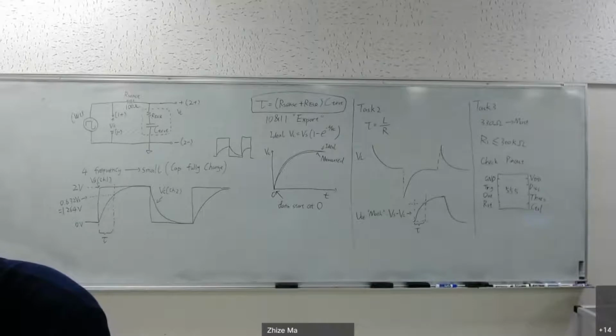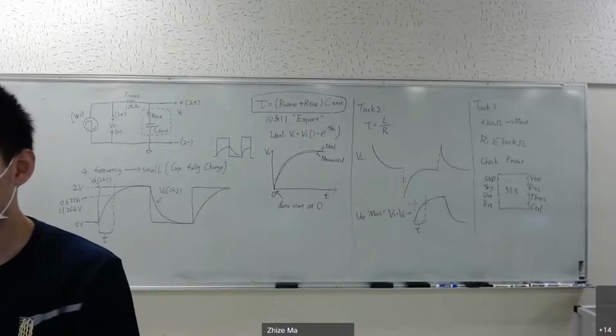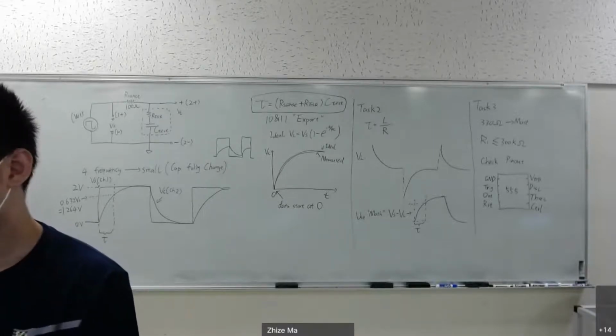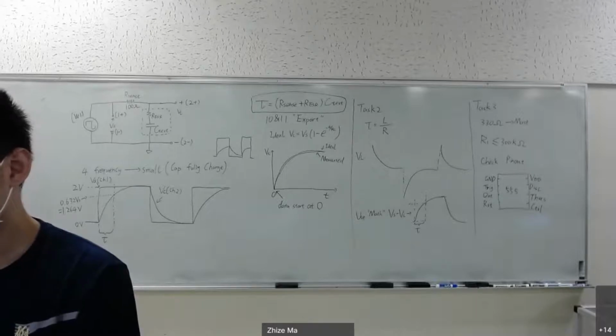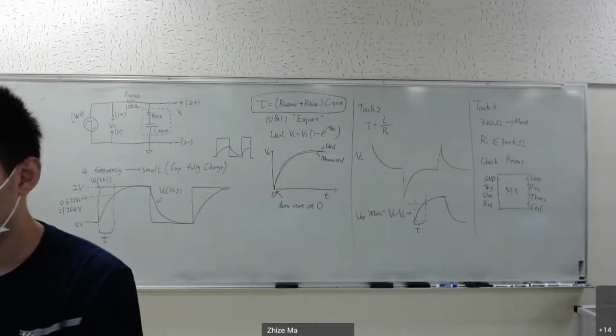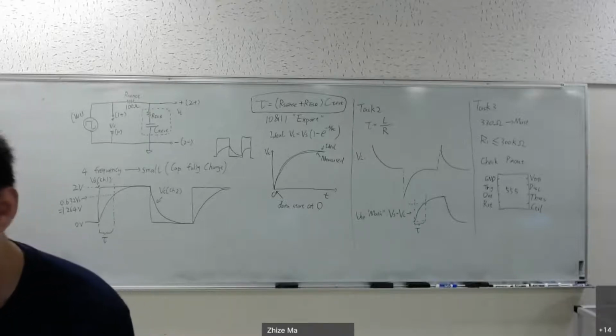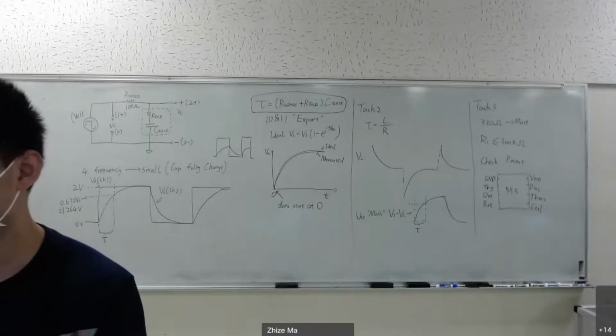As you noticed, in a real circuit, when you have R1 and C1, you cannot use any value you want. For example, for R1, since you are going to use the scope of your AD2 to measure the voltage at the threshold, and the oscilloscope has an internal resistance, if your R1 is too large, that will make R1 parallel with the internal resistance of the scope, and that will cause some issues.